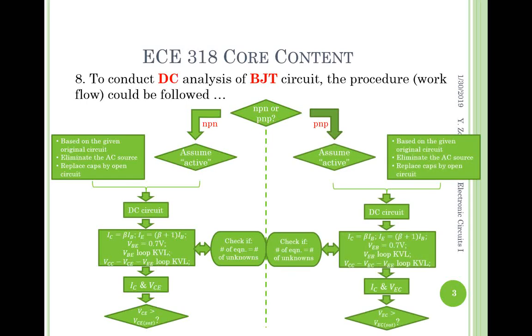Nothing different except the variables here. It's not VBE anymore, it's VEB, and not VCE but VEC. And we are checking whether VEC is greater than the VEC saturation.